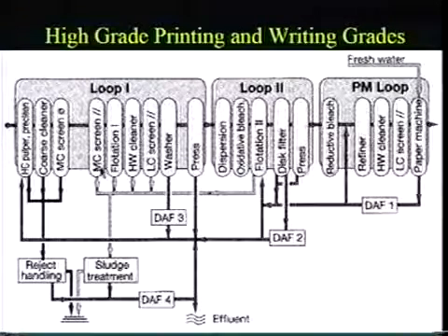Then we've got a medium consistency screen now with slots, flotation process, forward cleaners, low consistency, slotted screen, and then washer. So you can see all these 4 operations right here depend on inputs that are low consistency, so we keep those together. A press, that isolates water from loop 1 and water from loop 2.